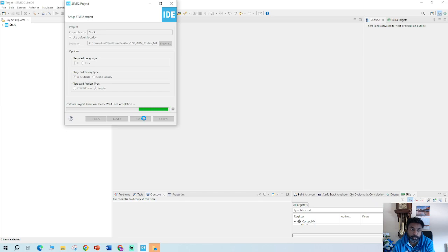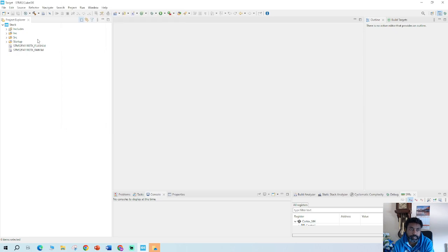So as you know, the source file generally comes with 3 different source files. main.c, and if you remember, it will come with the startup files, and it will have its linker description files. So as you can see, it's already generated that for us. Okay, so the source has system call and system memory, and the startup will have these 2 files, the flash and the RAM. So double click on main.c.